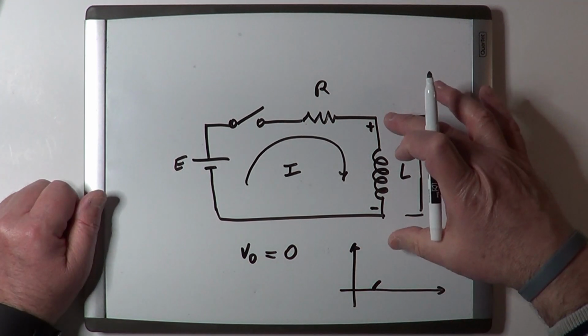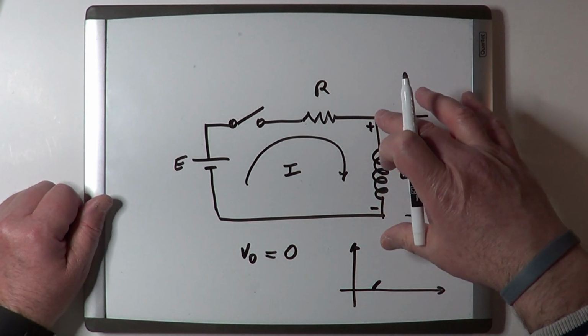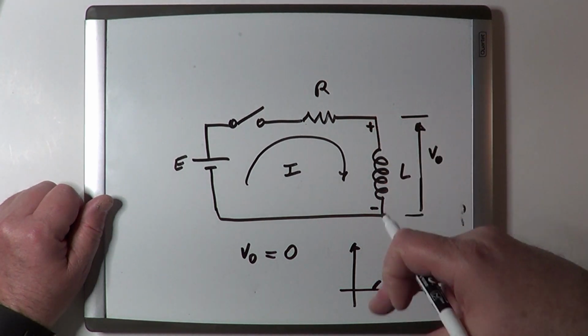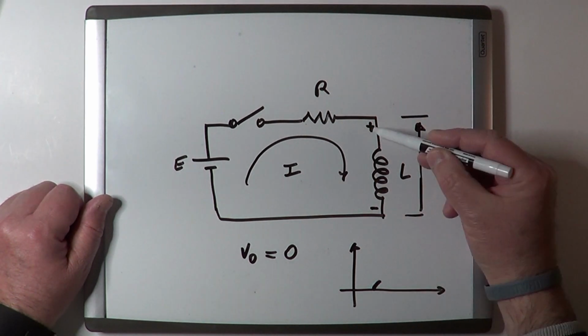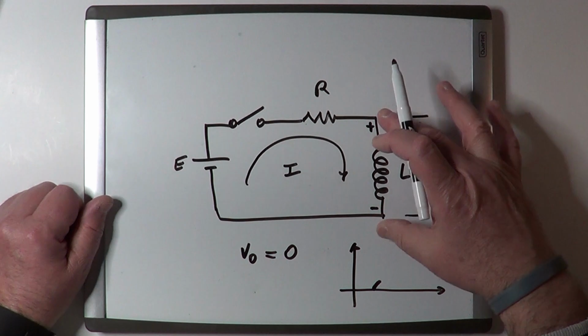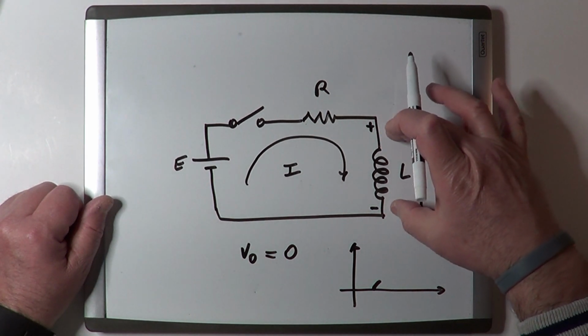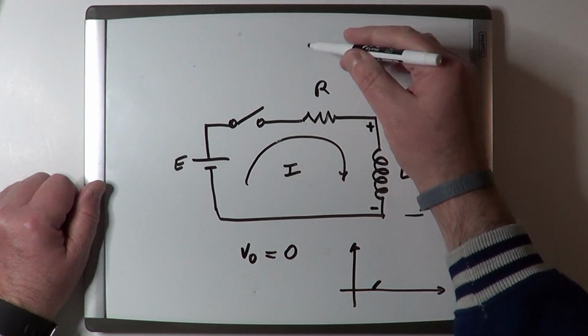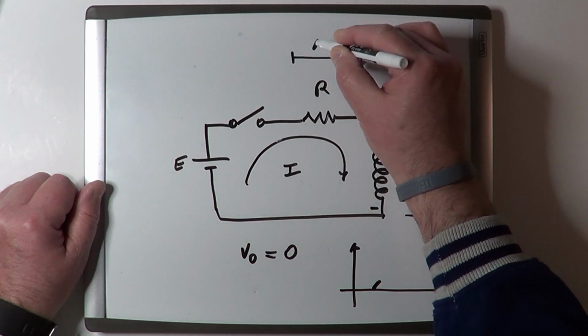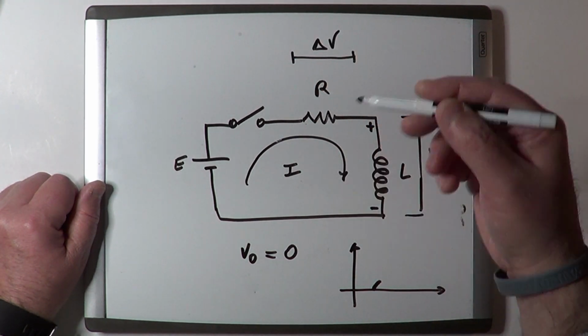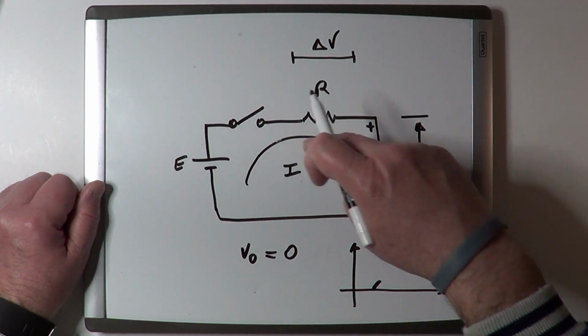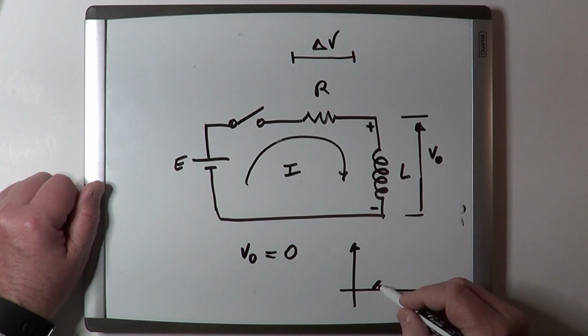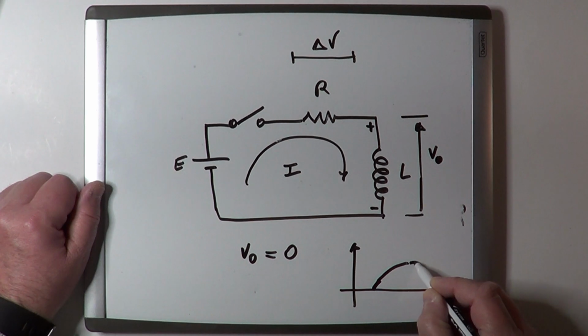But then the inductor starts charging, and while it charges and accumulates magnetic fields around it, this voltage across the inductor will start reducing a little bit at a time, and so a difference of potential will be created around R, which will keep increasing over time, and so the current across this series will start increasing as well.